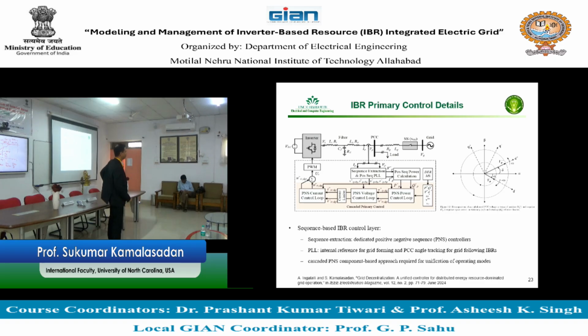However, if you are working on sequence combination, you have to know the fundamental sequence. That's a challenge, because if you look at an A phase, now my A phase is unbalanced. So A phase has positive, negative, zero. B is also unbalanced. You have positive, negative, zero. So generating that in a sequence representation is a little bit better as opposed to ABC to DQ. So for the single phase inverter, we did some work.